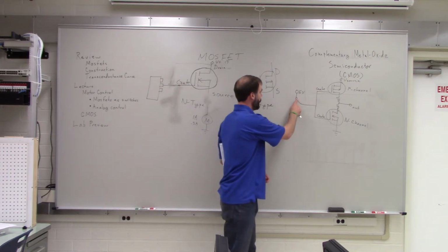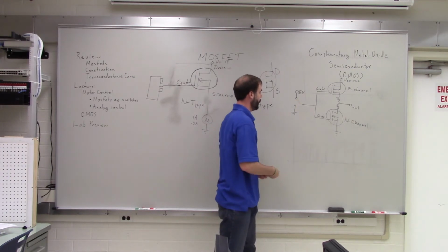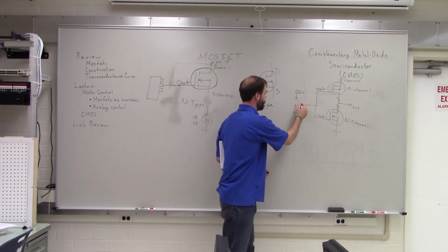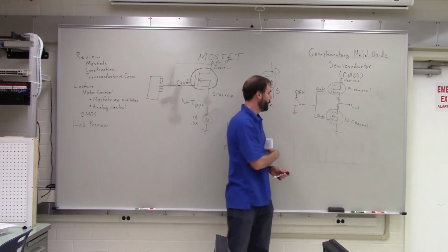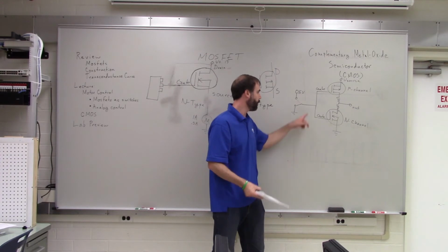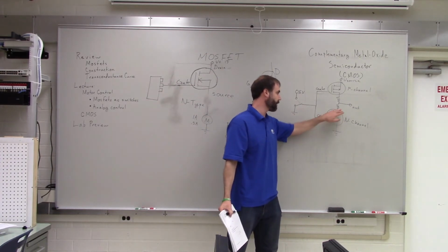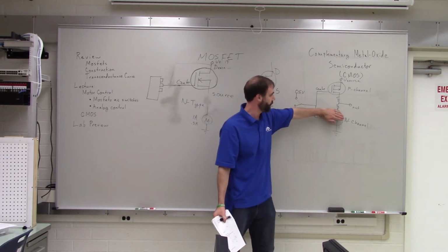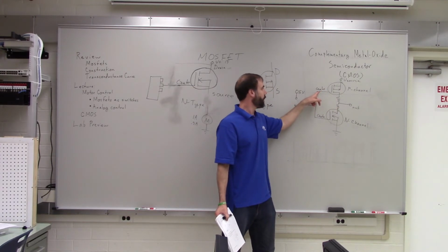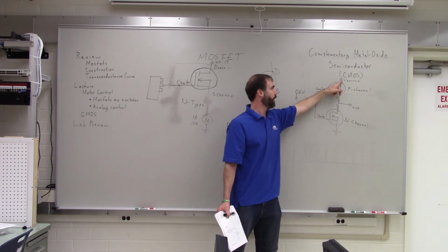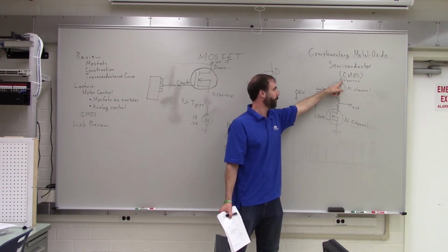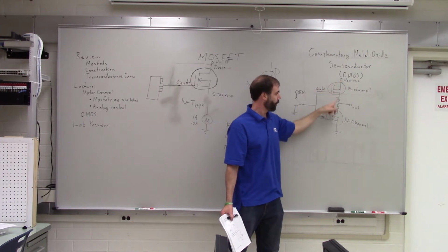If you put the switch in the other configuration, like this, now you've got a low voltage here. So a low voltage on the gate of an N-channel MOSFET means that it's open, so it's like it's not even there. A low voltage on the gate of the P-channel means that it's acting like a wire. So you've got a straight wire from your source voltage to the output.